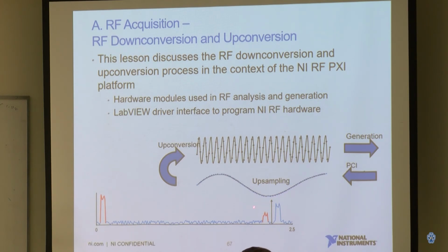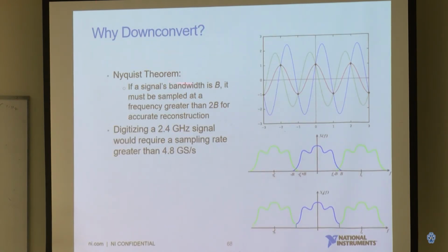So this comes out the concept: you down convert your signal, analyze it close to DC, and do the analysis. And when you send the signal out, you up convert the signal to a particular carrier frequency to transmit. So this is the concept of up converter and down converter. It just requires more cost and more money to do it.